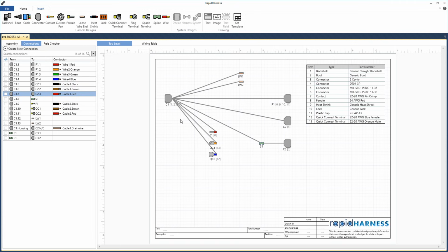So the next thing I need to do is arrange my bundles to model their physical layout. So if I click on one of these bundles here, I can right click on it, and I have a couple different options here. The first one here is for adding a layout point, and these are used if you just want to arrange things around the screen. If instead I wanted to have two things come together or split apart, then what I could do is add a branch point here. And we can also specify the lengths of our bundle as well. And this last option here is used for merging two bundles together, and this is if you have more than one bundle selected at a time.